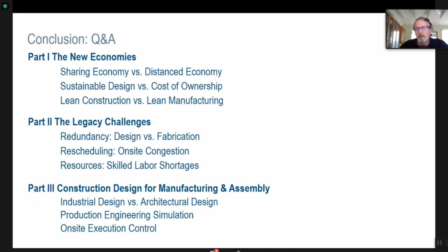For most spaces, they should be panelized, and the difference between a roof system and a wall system and a floor system is significant. I don't have time to go into it, but you always have to have a mixture, and it's not one or the other, and it's not one material or another. I think in California, for example, we'll continue to see some form of concrete construction for parking garages on a podium and wood frame on top for 3-4 stories. It's good for a walk-up. It's good for seismic. It's good for a lot of things. I think we're going to see hybrid systems, and focusing on one system only, I think, is a risky proposition.